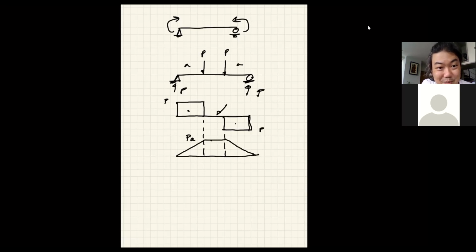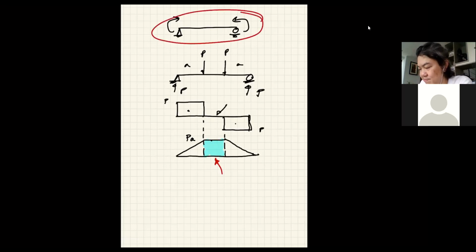Yes, probably. Probably again. How can you say probably? We have the correct shear force and bending moment diagrams, right? This truly is constant moment, ideally. And this is a setup of the beam in the lab where they want to truly explore the effect of bending moment on the beam right here. We assume that the shear is zero. So you have pure moment on one free body diagram of the beam, which is this free body diagram, right?